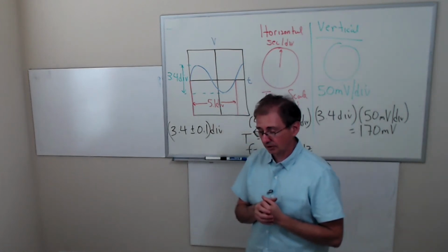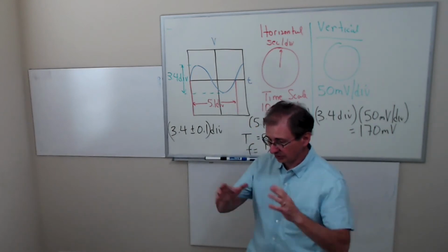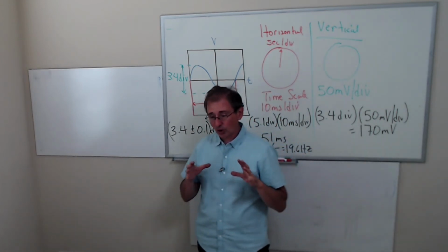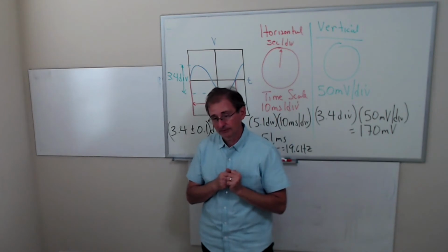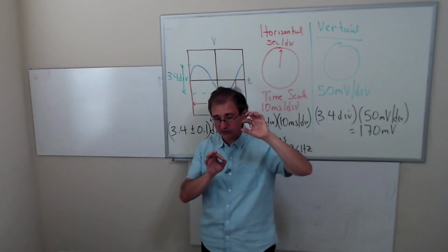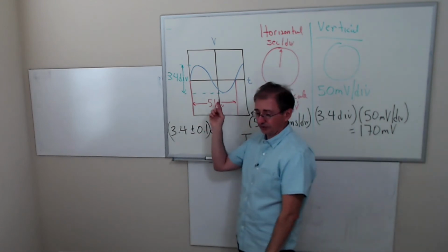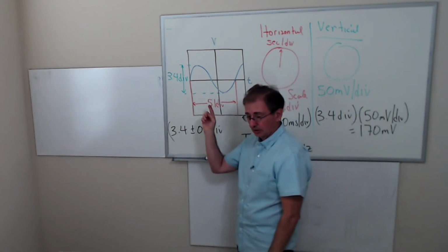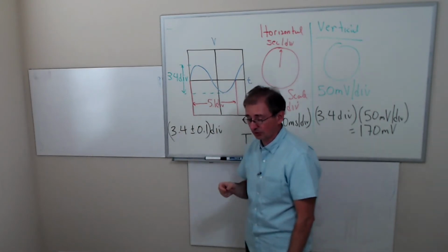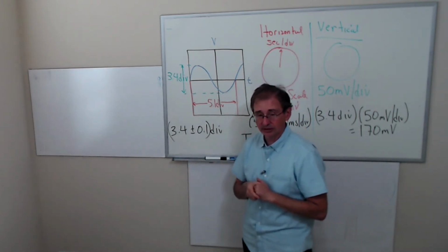And then there's 3 modes of triggering. One is called auto, which basically doesn't really do anything. So if you have a messy signal, your display is going to be a mess. There's something called normal mode, which means that if you set your criteria for triggering to certain values of the voltage and the slope, the scope will wait until those criteria are met, and then that signal is displayed. That gives you a nice clean signal that you're looking at.